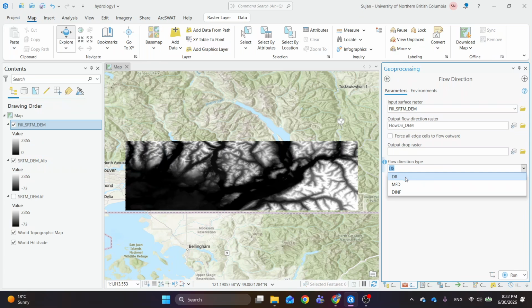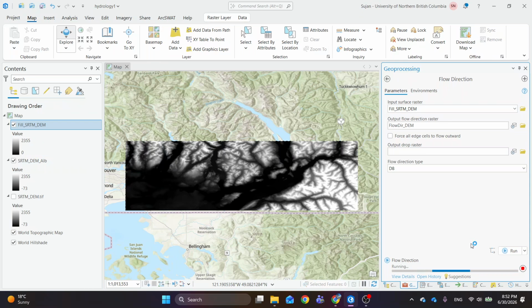of the ArcGIS Pro description of flow direction to understand what it is about. So for now, I'm just using this D8. D8 is like from the center, among 8 directions, which direction the water is going to flow, right? This is how it is defined, and it will have 8 values. So once you set all this information, you just go and hit run. And if you have to snap the raster to a specific raster, then you can always select the snap raster in the environment. If you want to check that information, you can go and check other videos that I have made.